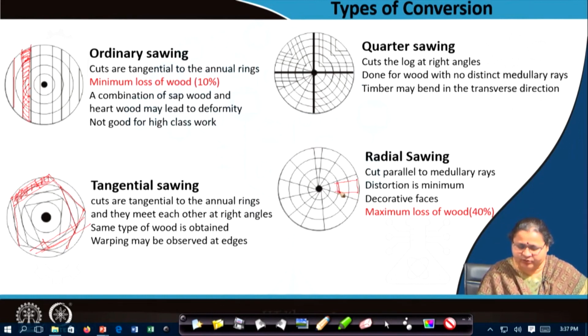So, you can get more or less similar quality wood. You can take out another piece from here like this. You may avoid some defect which may happen here. You can take this big piece and then convert it into your usable pieces. So, say some defect is here, you can take this portion and again take this portion separately.